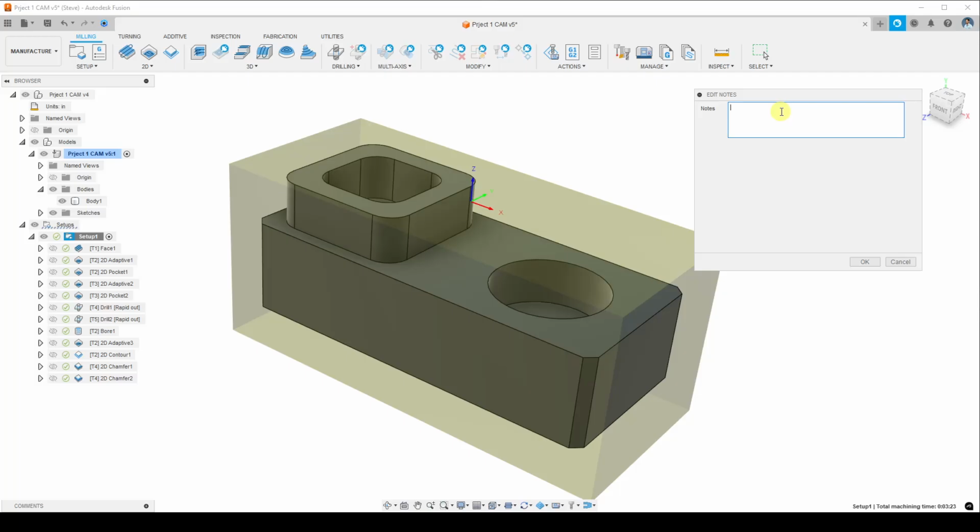So let's start with this. First thing I'm going to say is using G54 for a work coordinate system, WCS. And that just means that in the program we set G54 as the line where the information in the machine for the location of the WCS is going to be saved. So whatever machine it's using, when you're using it to find the stock material, you should have it save that information on the G54 line. Usually by default that's what happens, but this is just making it explicit.